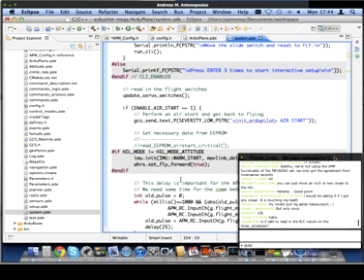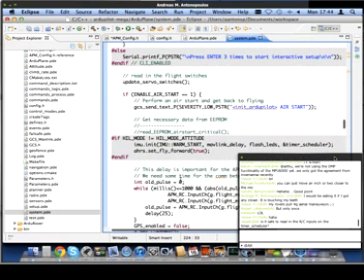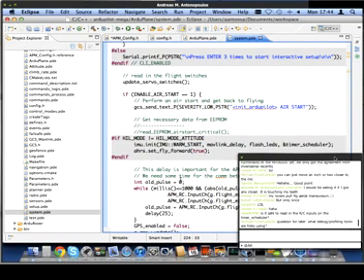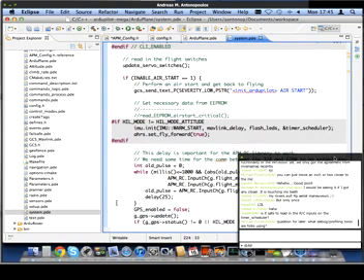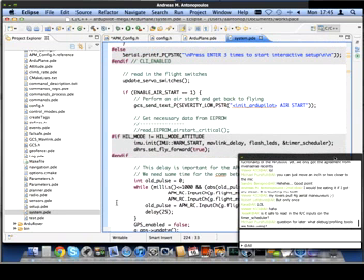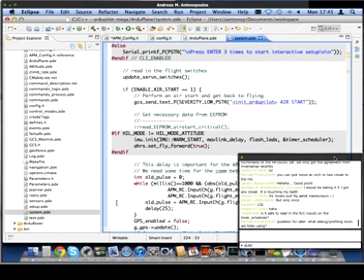Then you can see the code that allows for the possibility of entering the command line interface, where you hit enter 3 times to enter the interactive setup. That's a new feature we needed to add for the APM2 because the APM2 doesn't have the little slider switch that the APM1 had for allowing you to choose whether you're in flight mode or not. We needed an alternative way of saying whether you were going into the command line interface or into flight mode, and we decided the simplest was to hit enter 3 times, and so that's where it enables the little hit enter 3 times message, and then it watches for that inside the serial code in the Mavlink module.